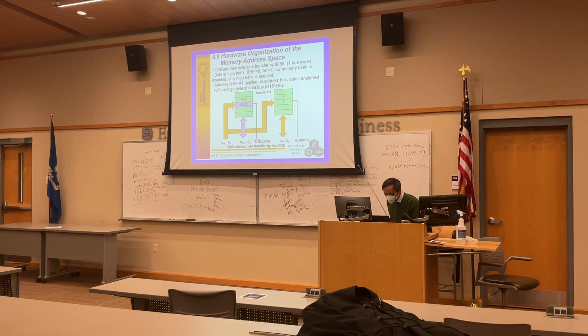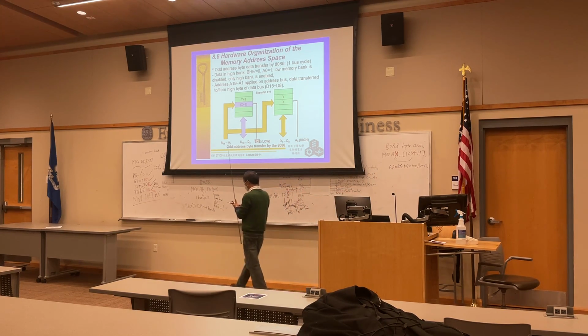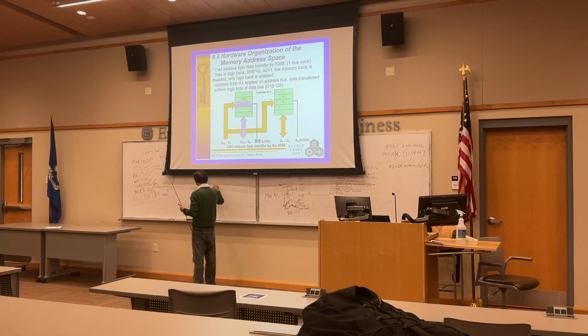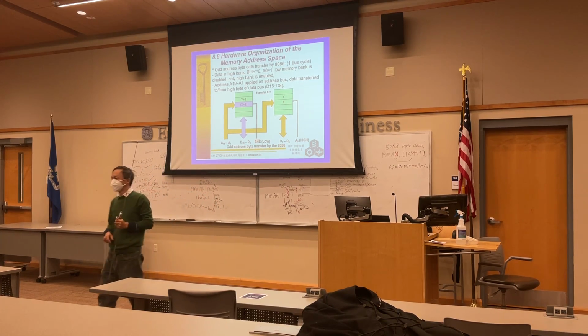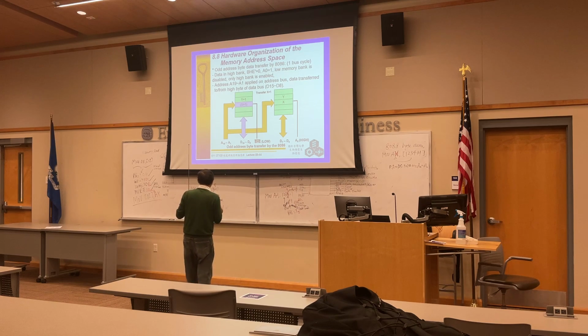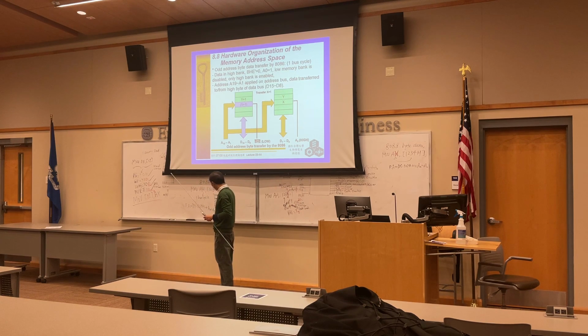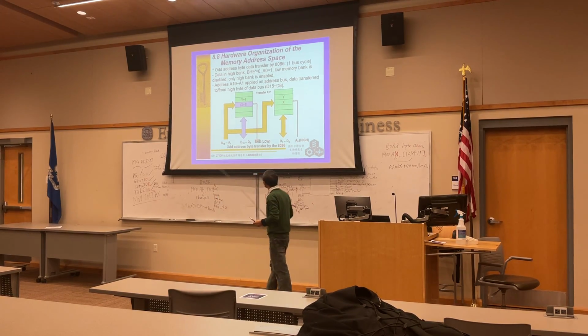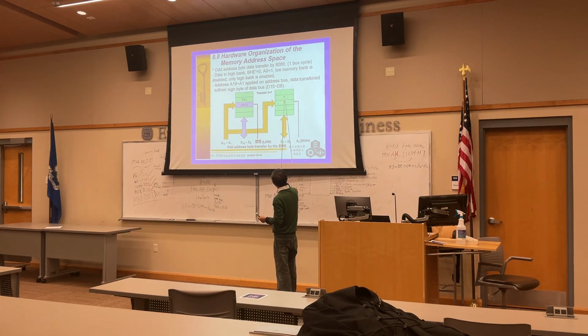However, if this one is in the higher bank, what happens? How many bus cycles? Still one bus cycle, because you still have byte data, only one byte. But now A0 is odd, so you should set Bank High Enable bar to 0 to enable the high byte, and disable the lower bank with A0.